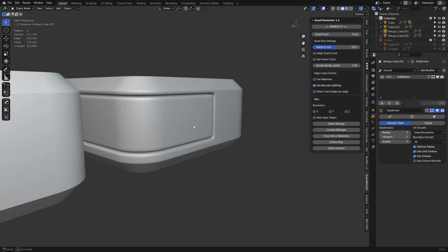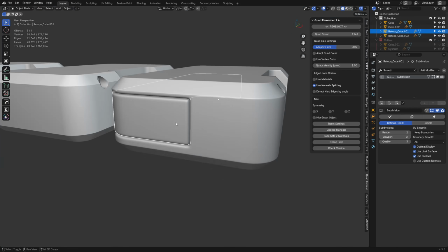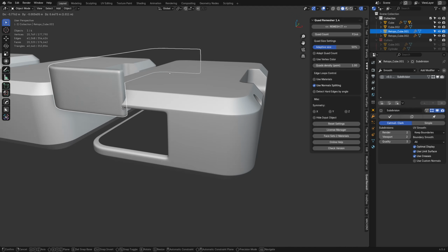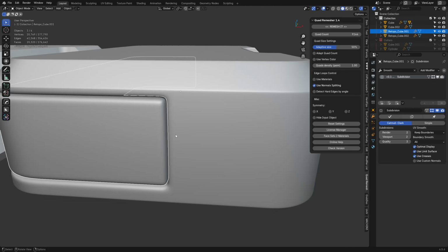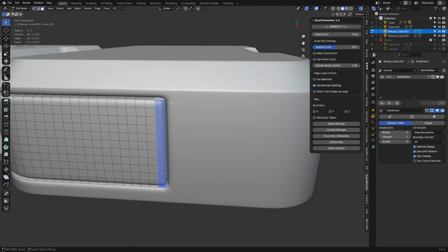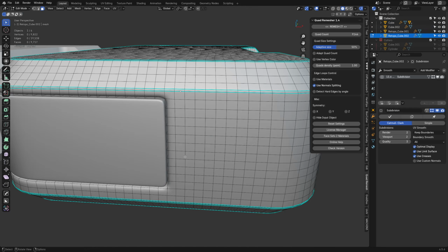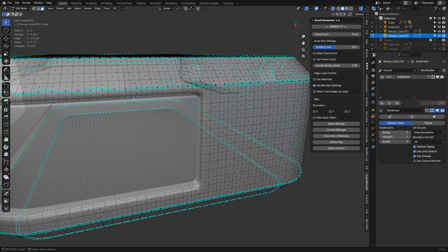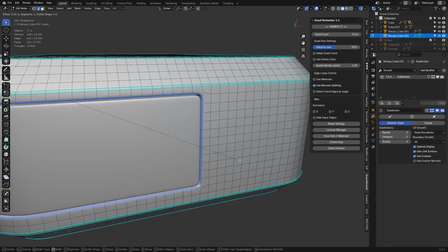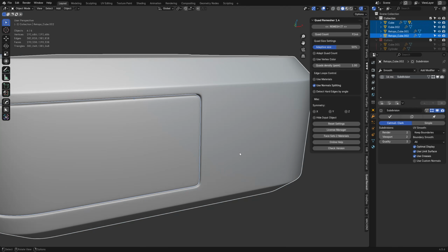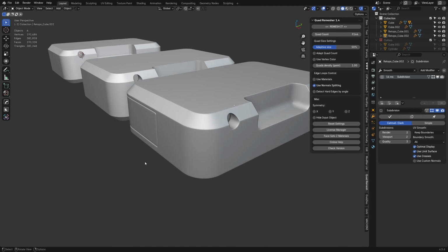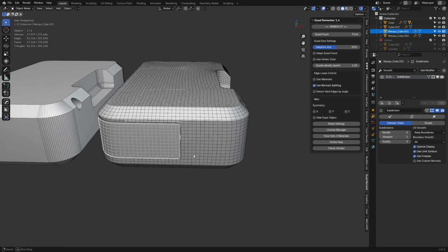So this is kind of the cool stuff you can do with Sub-D mesh. Like you can work with a non-manifold where it's not solid or anything like that. And we can always go back in here, select loops, alt-click that one, select boundary loops. I got that on a shortcut, but it's up there under select. So I can make that edge sharper if needed. I could do that same thing on the inside here because it's a big loop right now. So if you control your mesh and your edge flow, this helps out tremendously. But you can't always get away with it this simple with the quad remeshes usually. But it's just something, you know, to think about, some food for thought.